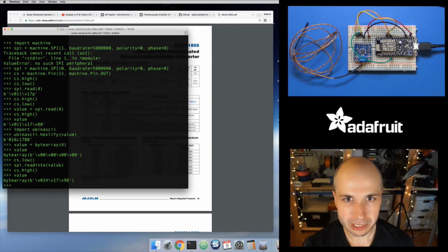Again, just something to think about. Don't worry too deeply about this if you're new to this. But it's just something to realize that, even though this is Python running on a microcontroller, it's still a constrained, low memory environment. So you still need to think about the heap and dynamic memory usage and what the implications are of using that a lot in your programs. And luckily with MicroPython, it's super easy. You can just allocate memory like this with one line. It's not hard at all. You can pass these buffers around. They know how large they are. So usually you hopefully don't run into buffer overflow kinds of errors and things.